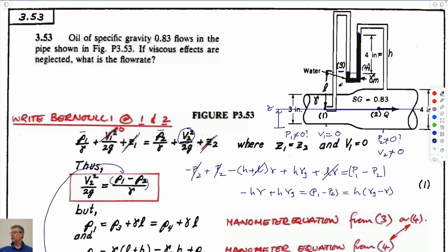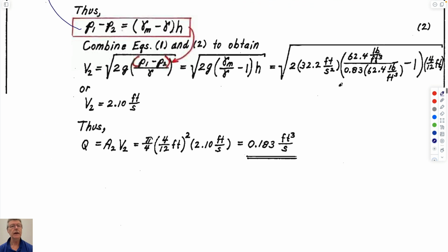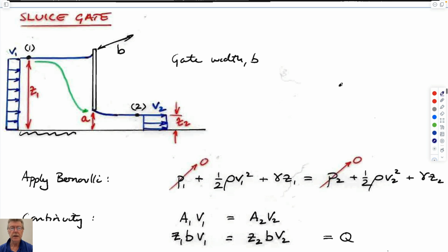Instead of measuring the pressure in this pressure transducer as 4,000 MPa and measuring the pressure in this other one as 3,999 MPa, and then hoping that the resolution of pressure transducers is a percentage of the full range. And so the reason for not wanting to use individual pressure transducers is you get a much more refined reading for a differential reading, because your range might only be the 1 MPa that's different, not the 10,000 MPa, which is the maximum scale on each of them. Okay? All words of wisdom. I know you're soaking it up on a Friday.